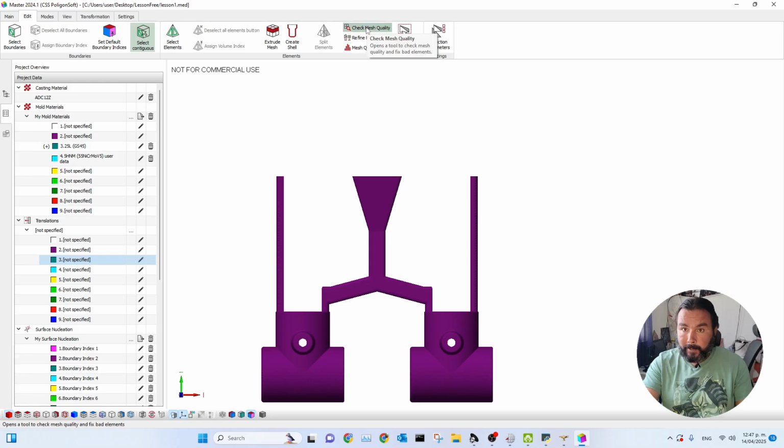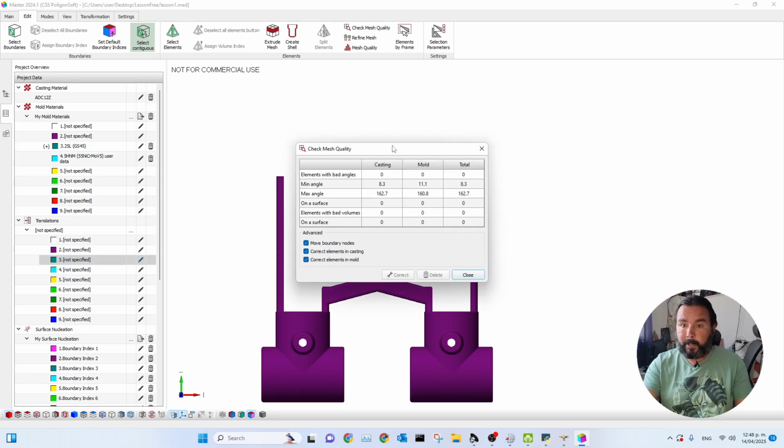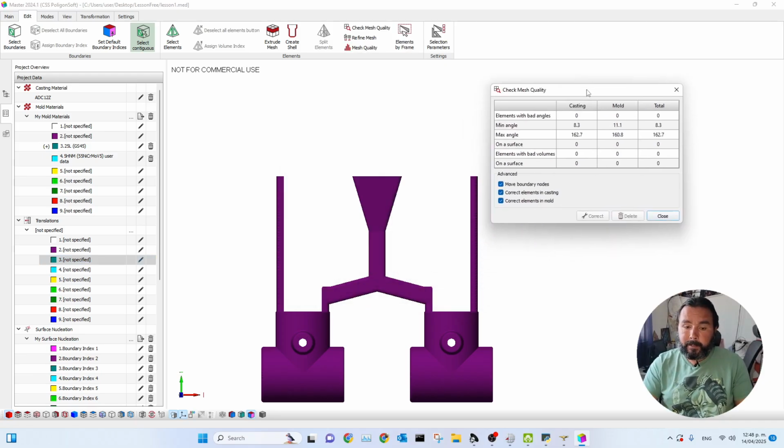This one here, check our mesh. Why do we need to do this? If you remember from the previous class, we executed a mesh correction command, but we only corrected the two-dimensional mesh. We created the 3D mesh completely automatically and performed no quality checks on it.